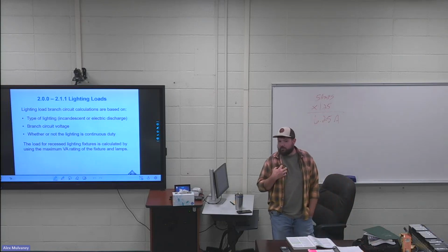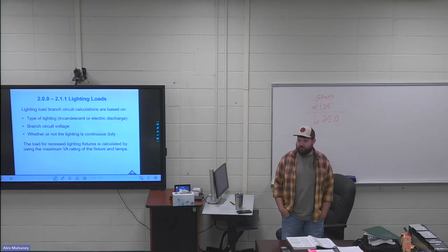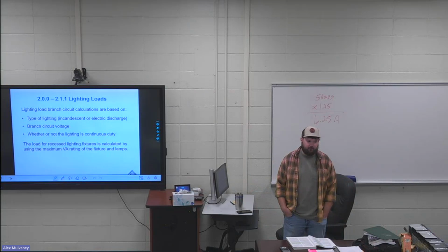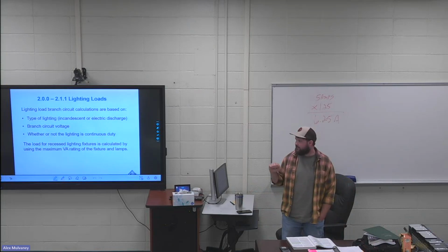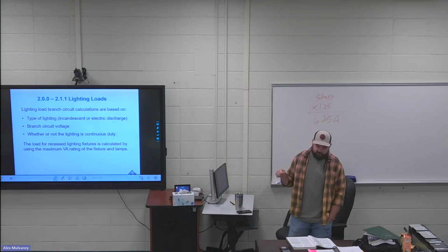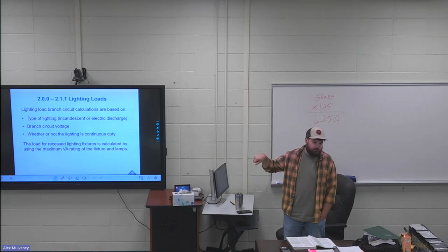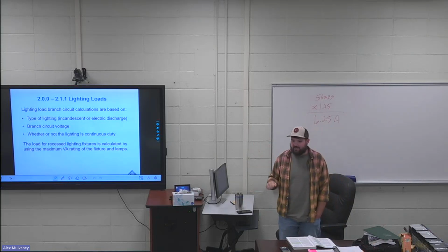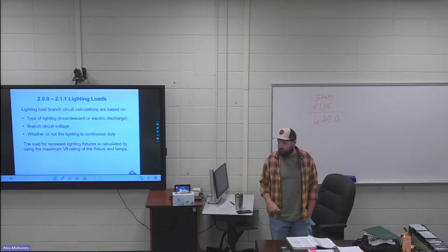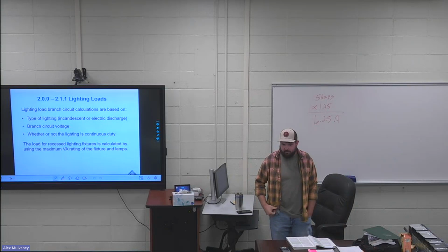Whenever I had to go back and learn how to teach this stuff, I didn't do a lot of load applications. I did troubleshooting and stuff like that. I was never doing the load calculations for buildings. It wasn't my background. So whenever I was doing my bank of questions and saw something like that, I would underline it, make sure that I had that, because that is important. If you miss that, multiplying by 0.8 or multiplying by 125%, it ruins your answer. It ruins the whole thing.